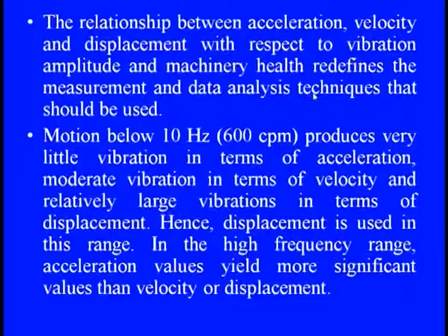If we are talking about a machine which is exciting below 10 hertz, it can produce very little vibration in terms of acceleration, moderate vibration in terms of velocity and relatively large vibration in terms of displacement. So, displacement is used in this range, and in the high frequency region the acceleration value is more significant than velocity or displacement, because when we are talking about high frequency, if we are talking about displacement,